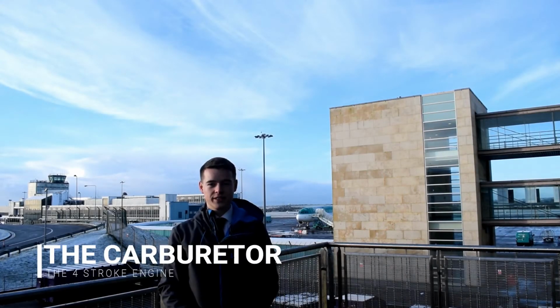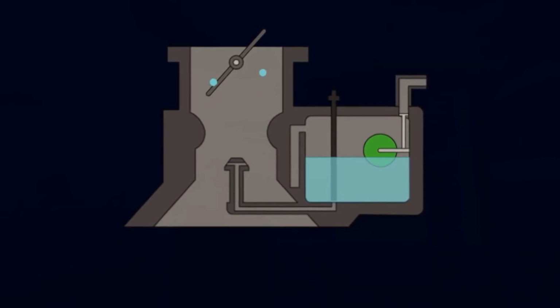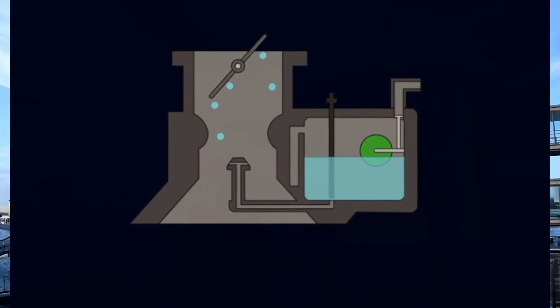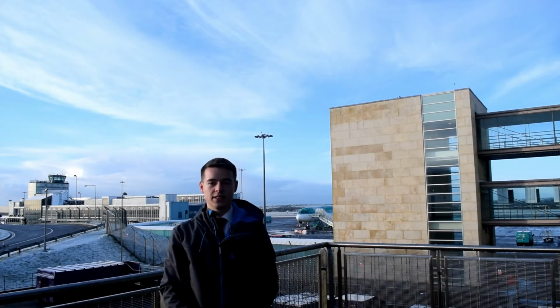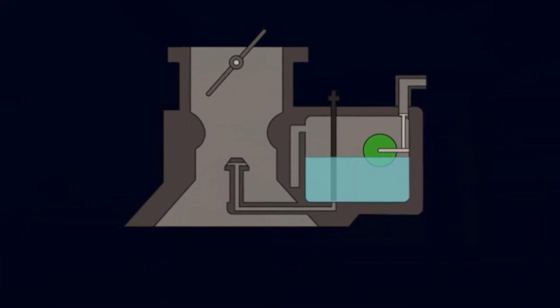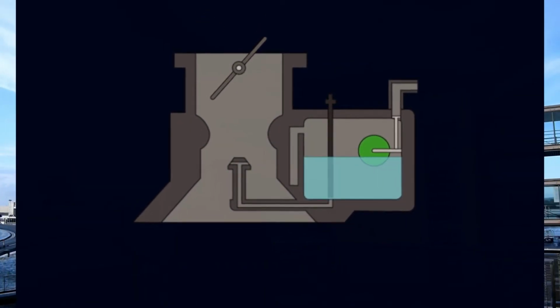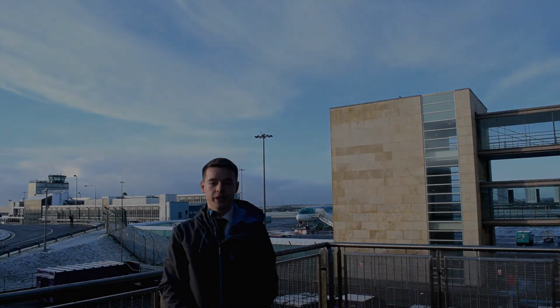A carburetor is a device that mixes air and fuel for the engine in the proper ratio for its combustion. Adjusting the mixture is essential during flight. As the aircraft increases its altitude, the density of the air entering the carburetor decreases. The fuel is being mixed with less air now because the air is thinner. To allow maximum air into the engine, you must keep the fuel-air mixture rich.